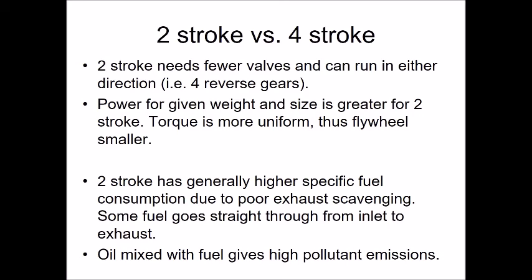The other thing is that with two-stroke engines, the oil is also in direct contact with parts of the process. So the air rushes over the crankcase as it comes in, and in doing so, it's going to pick up a bit of oil with it. So we're going to have a high oil consumption. We're also probably going to have oil combustion that gives us even more smoke. So these things actually are inefficient. They're filthy, dirty. They're noisy. They make a bit of a weird whining noise, as you're going to see in a minute.